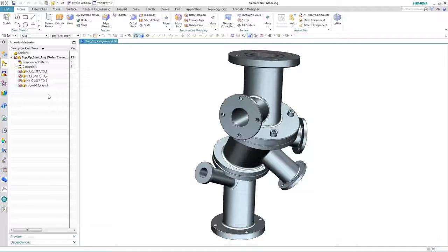Reducing assembly complexity, reducing material usage, or weight reduction are three reasons why you might employ a generative design tool such as Topology Optimization. Now, Topology Optimization is a form-finding process. It can start with a number of design rules or goals and then explores a number of possible permutations of a solution to find the best option.